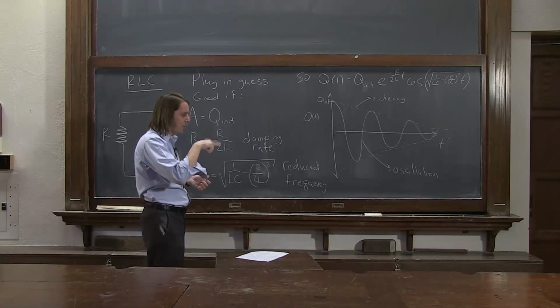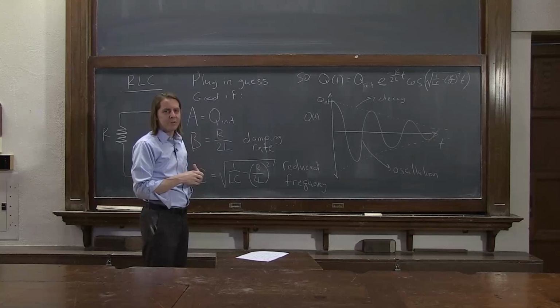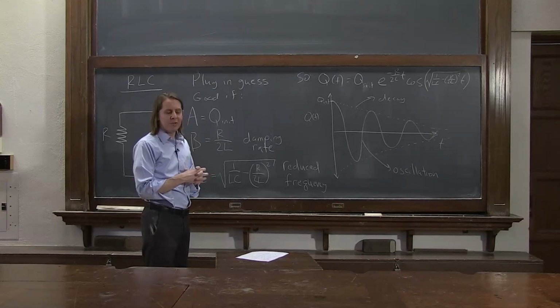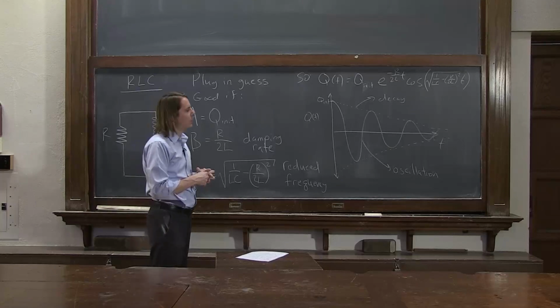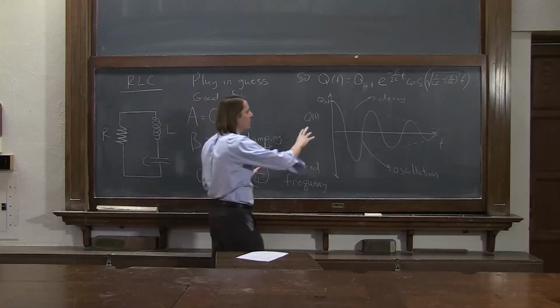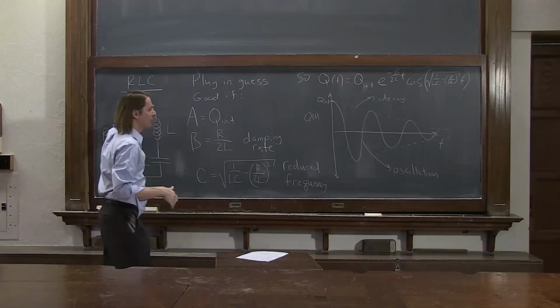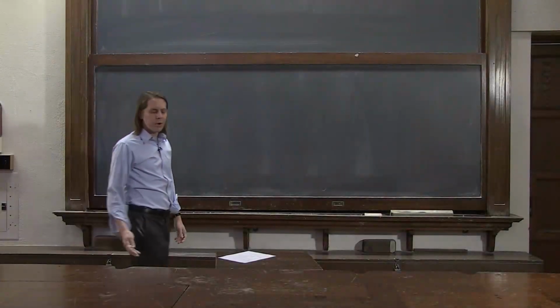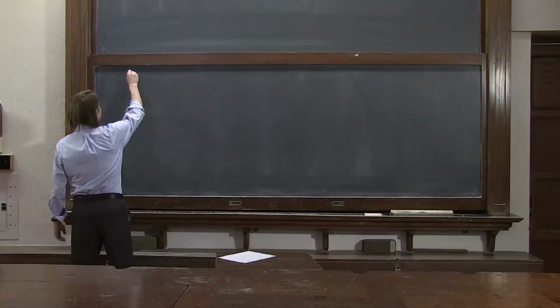And the inductor has a huge number of turns inside that inductor. That's a lot of really thin wire, and therefore a reasonable amount of resistance that's hard to get rid of. So anytime you demo an LC circuit, you're always really demoing an RLC circuit. So you always have some level of damping in the circuit. The RLC circuit has different damping regimes.